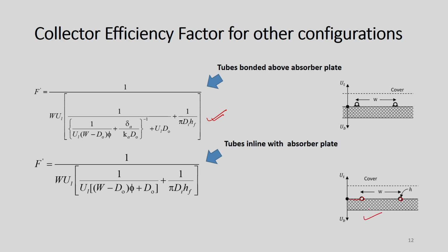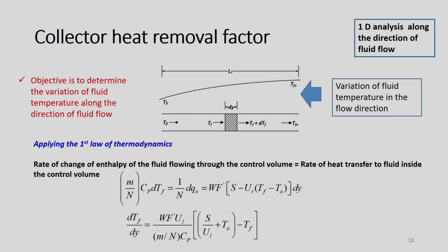So, if this is the case, then we need to use the expression for F dash something like this. Okay. So, straight away you can use those expressions for calculation of collector efficiency factor for these two configurations. Now, come to the analysis part for collector heat removal factor.